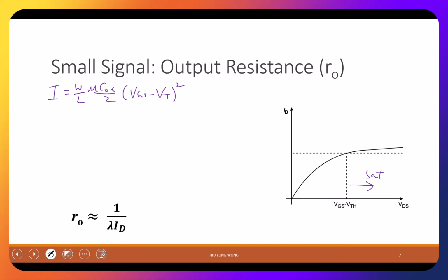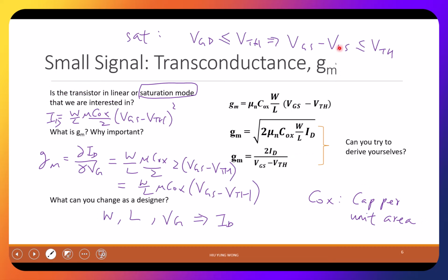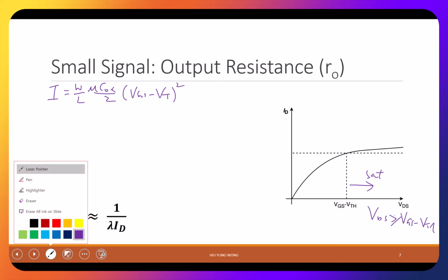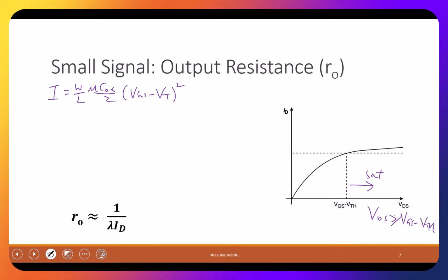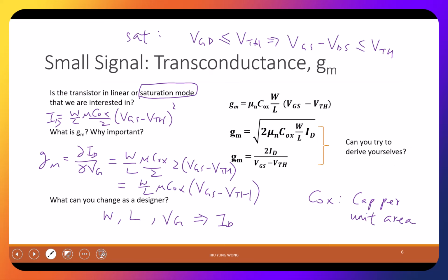And again, here we repeat what we said earlier, VDS larger or equal to VGS minus VTH. That is saturation. And like what you said, VDS moves to there, VGS minus VTH, right? So this is the saturation, which is almost correct. The current is almost constant. It does not depend on VDS. But now you probably will argue with me, it does. It increases a little bit when I increase VDS, right? So this is called channel length modulation.